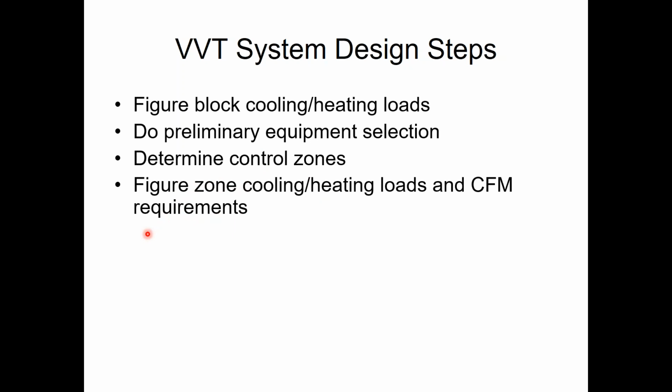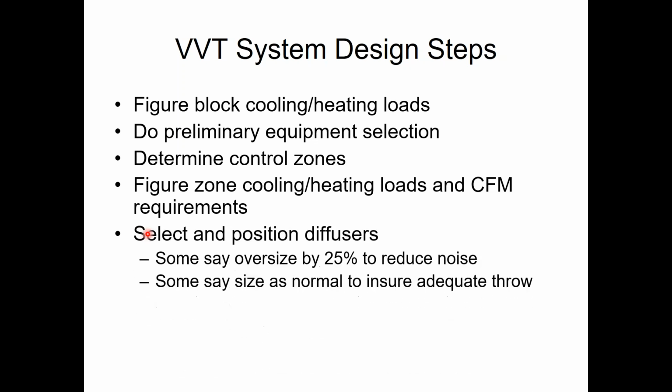The load will tell me, if I know the load of the zone and I know I'm going to use a 55-degree design temp, then I can calculate the CFM based on that, just like I would on a constant volume job. I'm going to determine where these diffusers are going to go physically in the space.